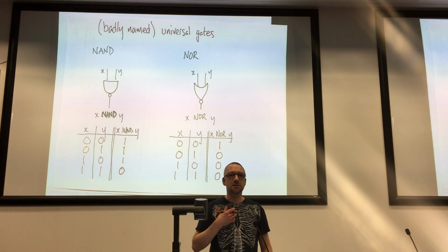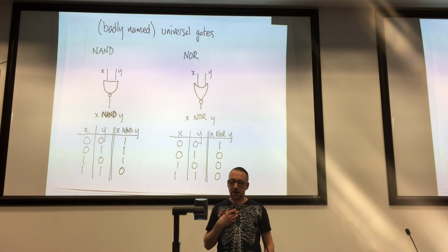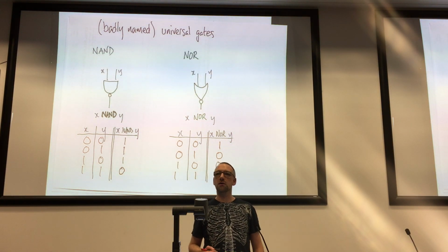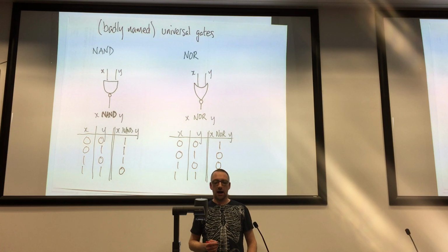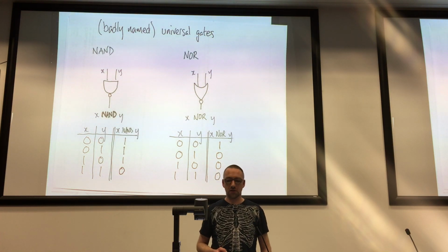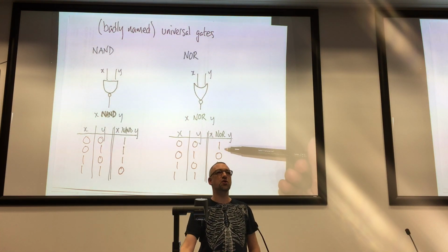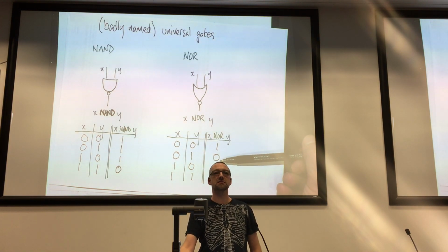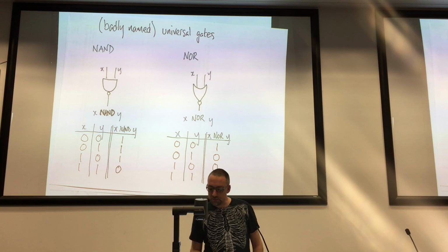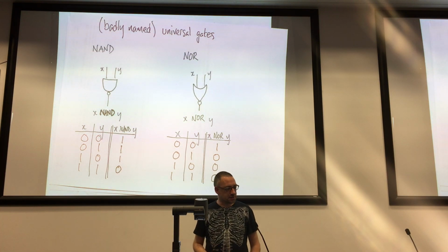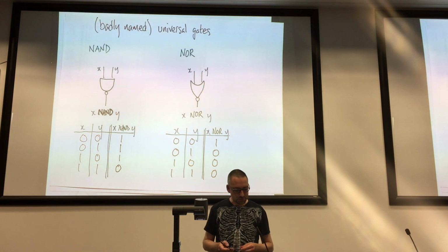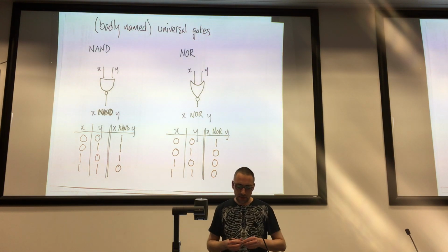So if you think about what we're saying here, right? Negated OR, that's a NOT of an OR, and De Morgan's rule tells us that's a pair of NOTs. And indeed, X NOR Y is true only when both X and Y are false. So there's a connection with De Morgan's rules. Okay.